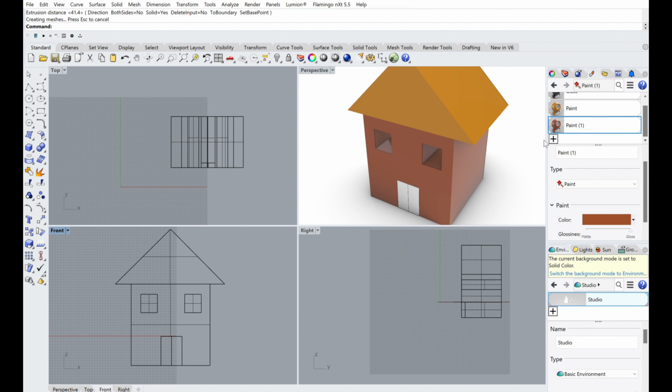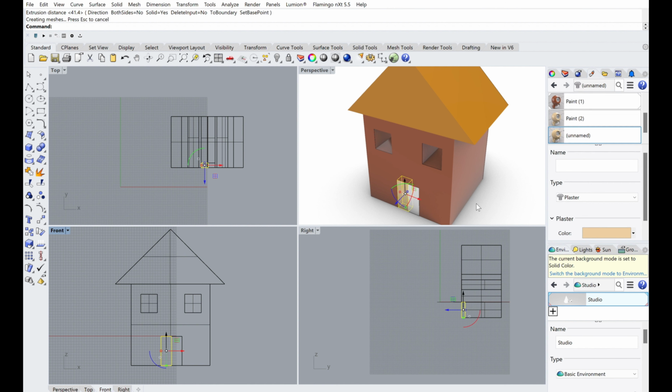So we're going to drag this down, and I'm going to choose a paint material, and then we're going to go to color, and we're going to go here where the select tools will come up. So we can choose from a tan, and most doors are tan. So let's give it tan. Assign one tan. And then the other side tan.